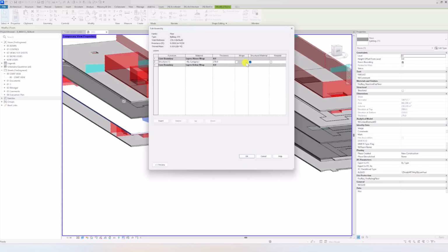Then we go into structure, which is how the floor, all the different layers within the floors. Sometimes you will have several layers here. What I usually do is actually then select it. I'm going to insert the empty one. I just select those, every layer except one, and just delete those and just make the thickness the same. So 270 is the thickness of that slab.